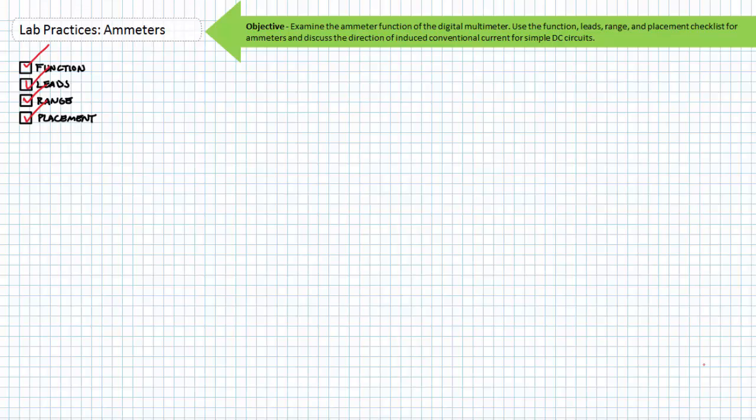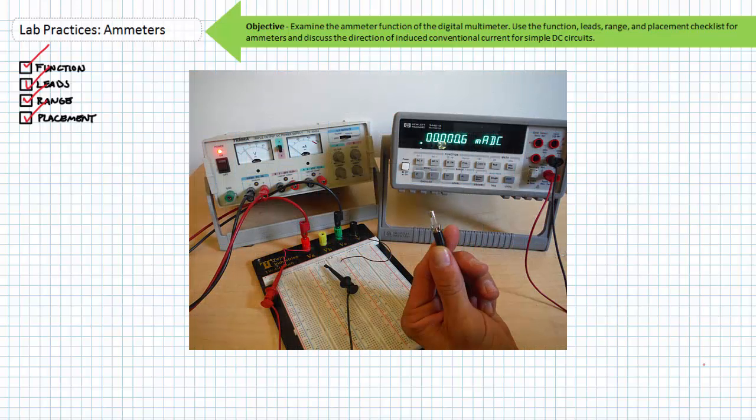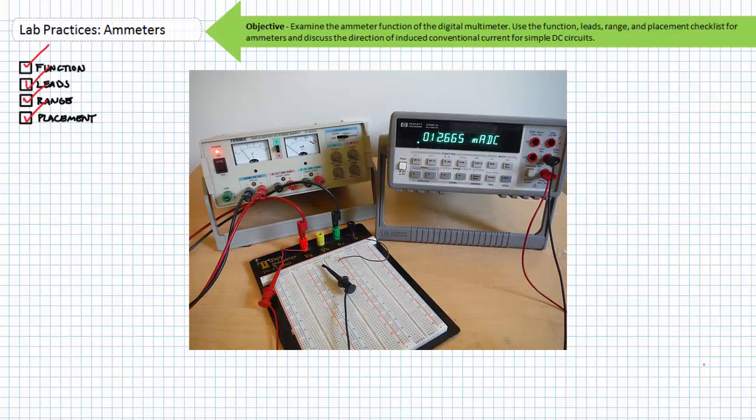Sometimes it's not your circuit. Sometimes it's not your lab partner. Sometimes it's faulted instrumentation that is inducing an error. Here's a picture of a DMM in ammeter mode with the input fuse removed. Ordinarily, a 5-volt source supplying current to a 390 ohm resistor would induce 12.8 milliamperes of current, but we're observing nonsense, even when the ammeter is correctly placed. When a functional fuse is reinserted, we're observing close to our anticipated value of 12.8 milliamperes.